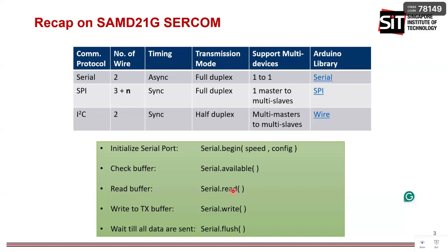Probably you would have already used Serial.print, all right? Here, we can also use .write to write to the transmission buffer, right? .read and .write serve similar functionalities. If you want to receive serial communication data, you use .read.